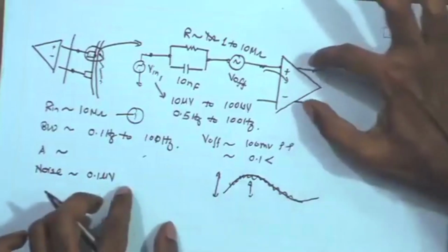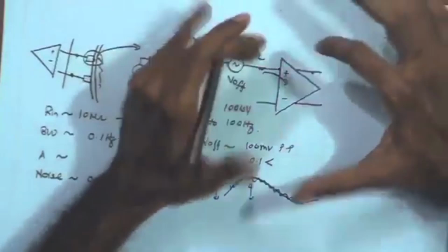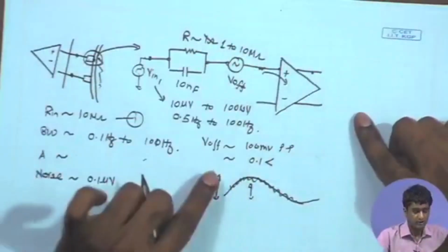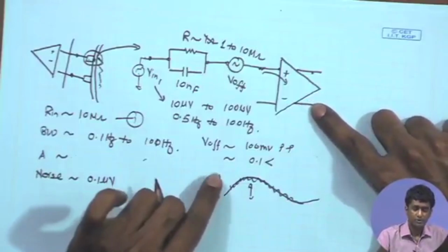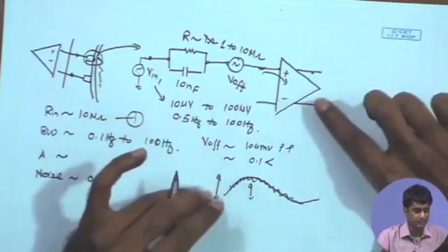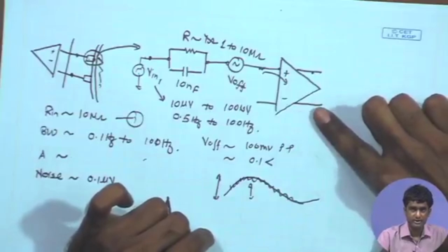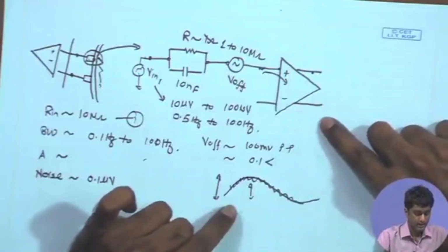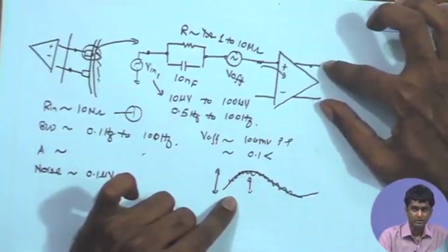Now, if we look at the supply voltage, suppose for 180 nanometer CMOS technology we are targeting low power design, and for that we have chosen the supply voltage around 1 volt. In general, for 180 nanometer technologies you can have a supply voltage up to 2 volts, but for low power design we can go for 1 volt. So, assume that the supply voltage chosen for this front end design is around 1 volt, and in that case the maximum swing at the output of the amplifier can be 1 volt.